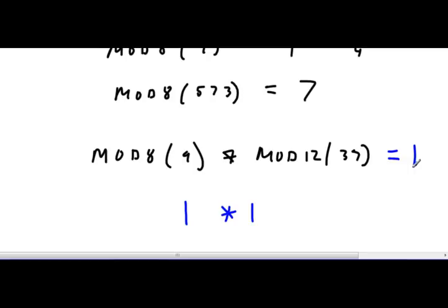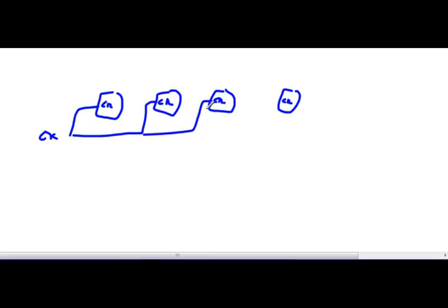Okay, now, if I go, and I've got a bunch of JK flip-flops. And so I got this clock thing, CK, CK, CK, CK. And I got a clock out here, clock pulse, and it hooks up like that. What would we call that counter? We would call it synchronous. It happens when the clock happens. Okay? Synchronous, something like that.